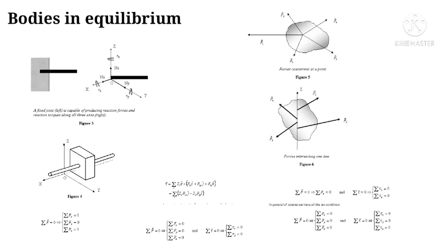Recall that if the sum of the forces of a system is 0, the torque is independent of the origin. Thus although in the beginning I used the fact that the torque about that point is 0, it is true about any point once the force equation of equilibrium is satisfied.